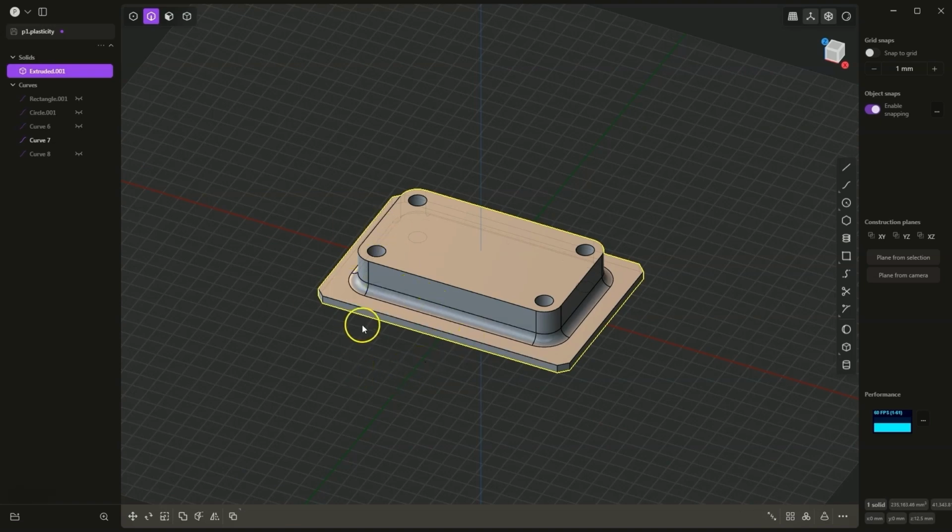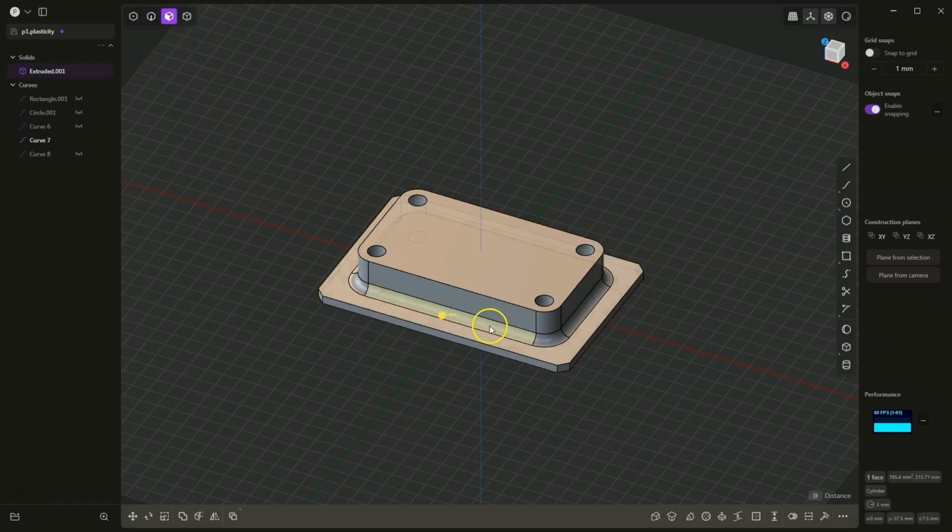If it turns out that we added the wrong radius, and we want to change the radius value, switch to face selection. I click the 3 key on the keyboard, select the radius, and we can change the radius value. Here, similar to edge selection, we can select it with the Shift key, or we can press the Alt key, then the entire radius will be selected. By dragging, we can increase or decrease this radius. We can also press the D key and type 2, hit enter. In this case, we specify an increase in radius by the entered value. Okay, we can leave it like that.